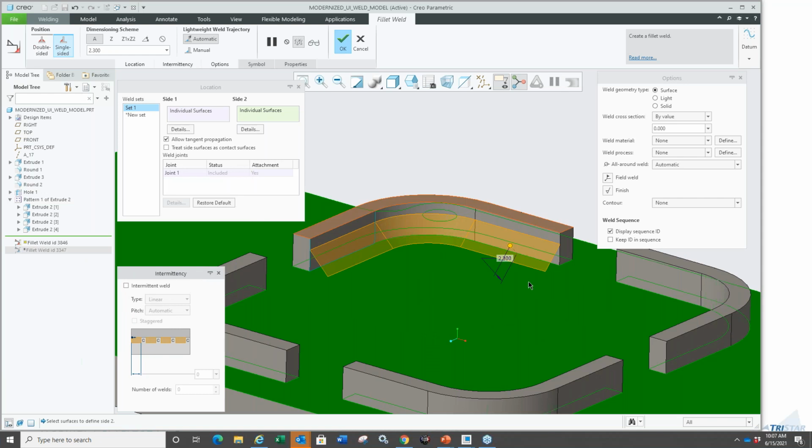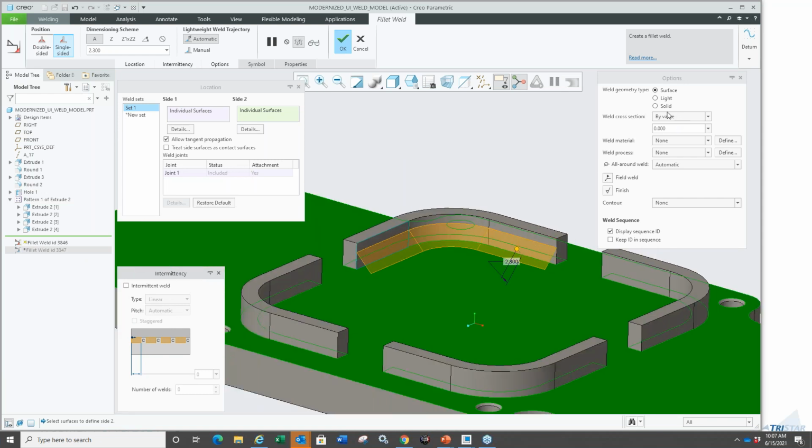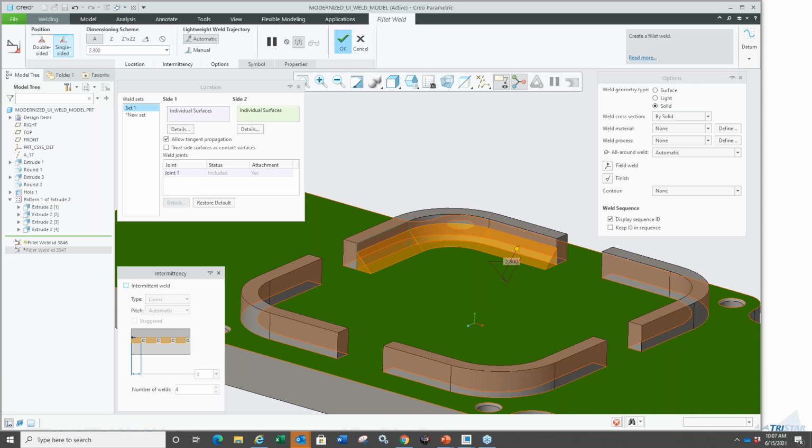So now that it looks like it's a surface weld, it's not closed, I could just go to solid weld right in here. I could just go to intermittent weld. Intermittent used to be an option in the dashboard. Now we have a separate panel with a lot more control options. And maybe I could set it to a specific value for that and number of them. I can just use end with weld, so it evenly spaces this out within those.